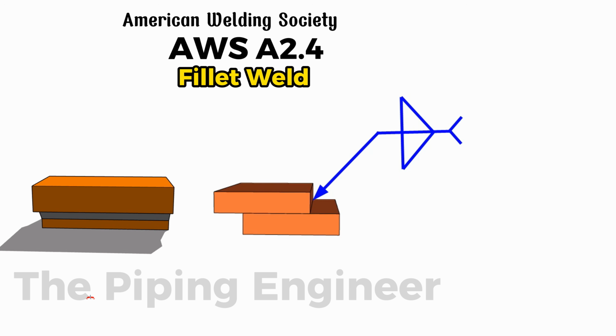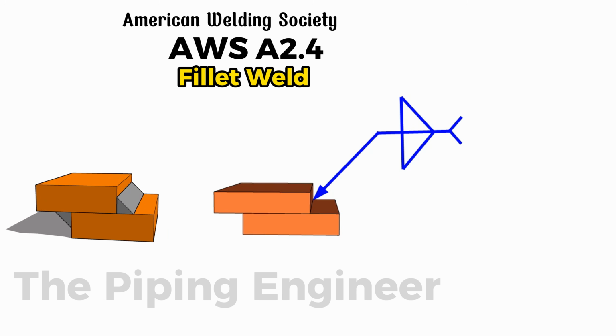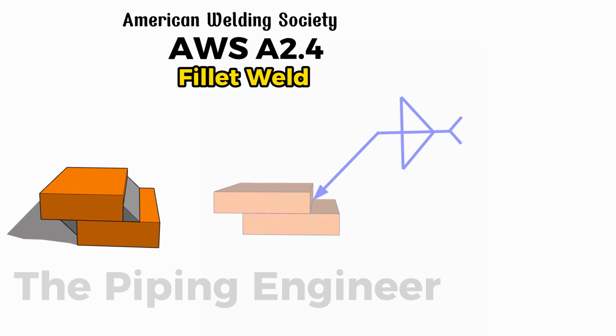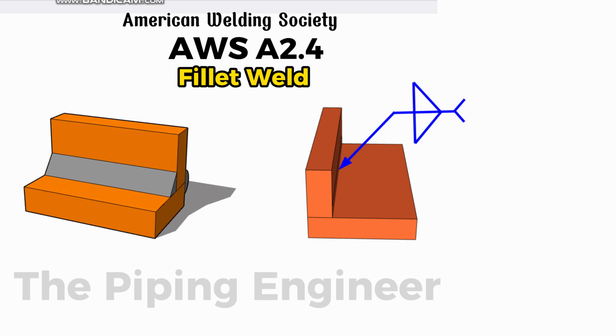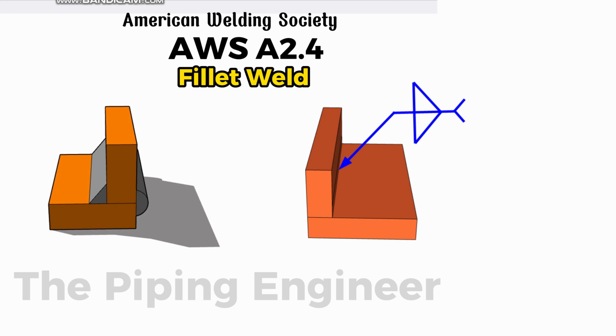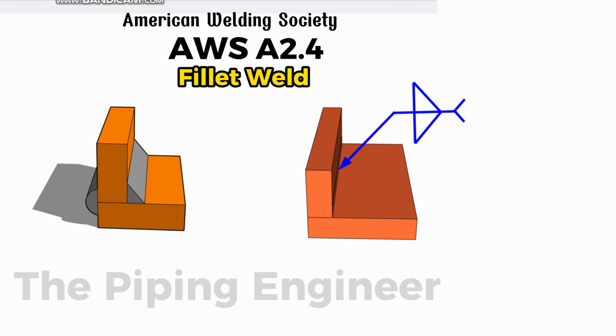This type of joint is widely used in structural and piping fabrication due to its excellent load-bearing capacity and relatively easy fit-up preparation. In corner joints, the edges of two members meet at an angle, typically forming an L shape, and a fillet weld is deposited along the inside or outside corner to secure them firmly together, providing strong structural integrity at the edges.